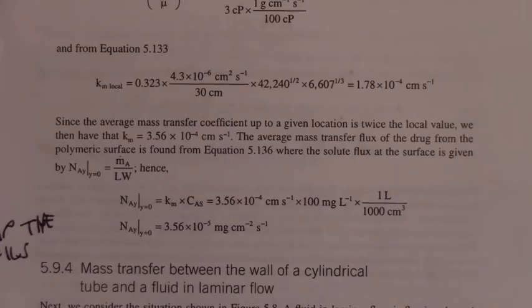So that's laminar boundary layer theory as applied to diffusion from a flat plate. And we got some interesting results from that. We see naturally where the Schmidt number comes about and how we interpret the Schmidt number in terms of the thicknesses of the momentum and concentration boundary layers.